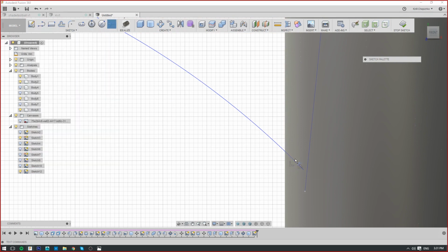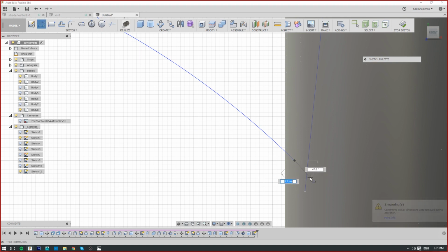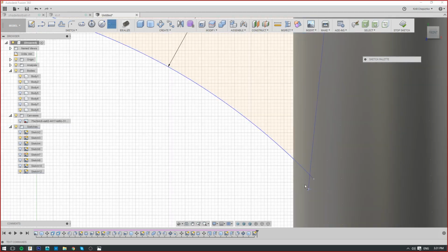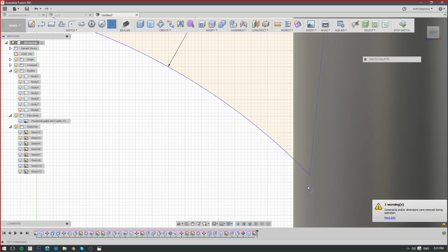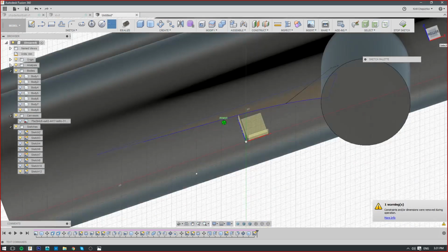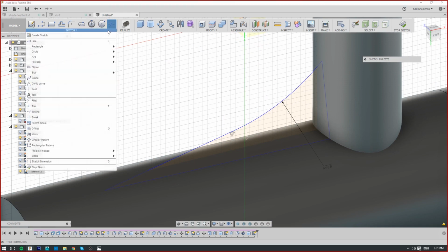It looks like I will have to see, there was an extra one there. I'd rather redraw. It's a bit scary with that fillet. Yeah. But since you know about those ends and you keep them in mind, it's okay. So can you delete those lines? There's also a tool called Trim. I also have it in my panel. It's in Sketch, Trim right here. There's also a shortcut for it, T.